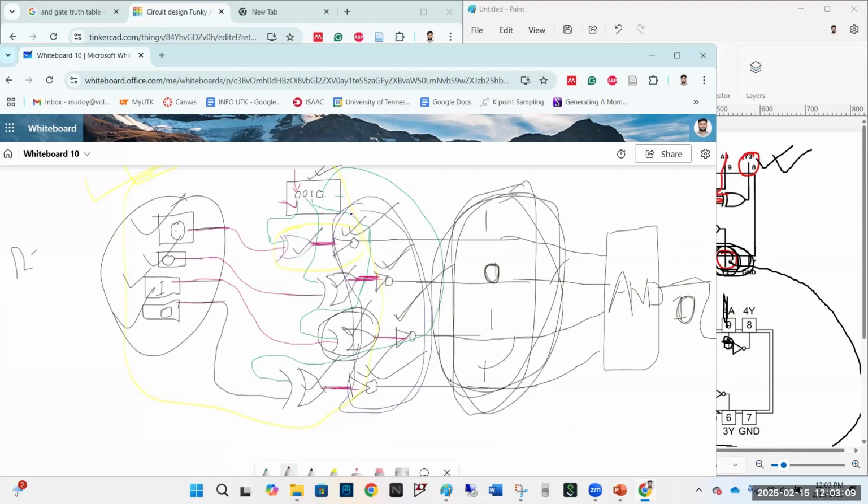We have connected the XOR outputs to the NOT gates, and we currently have the NOT gate outputs. Now, as we mentioned, we need to place an AND gate and deliver all these outputs of the NOT gates to the inputs of the 4-input AND gate. So we will need a 4-input AND gate, right? And we will connect the 4 outputs of these NOT gates to the 4 inputs of the AND gate.